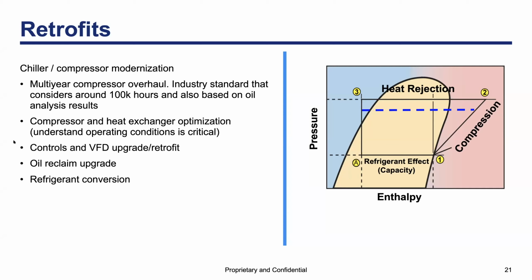This is key. Understanding what is the minimum requirement at low loads will guarantee a stability of the unit, especially at partial load, but more important at low loads. Understanding these limitations and operating conditions will help you to determine whether a VFD is a good addition or upgrade for the equipment, whether it's a compressor, a fan, or a water pump.